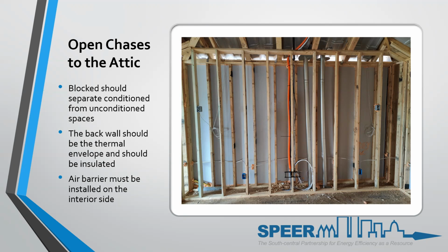But now you have an opening at the top. Doing it that way, you now have the flue pipes exposed to uninsulated sheetrock in front of them, which again is not a good way to do it. There have been several times that I've gone out on either an energy audit or a warranty claim for a builder because the homeowner says that that room is overheated. And the minute you walk into the home and you look down on the garage and you see where the water heaters are and you look up and know that that's where the bedroom in question is, you know that that's going to be the problem. You go in with an IR camera and you see 2 active flue pipes heating up that space behind it, therefore transferring heat into that room.